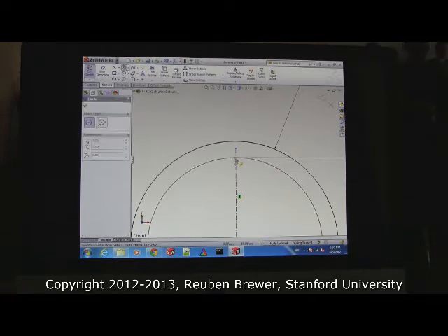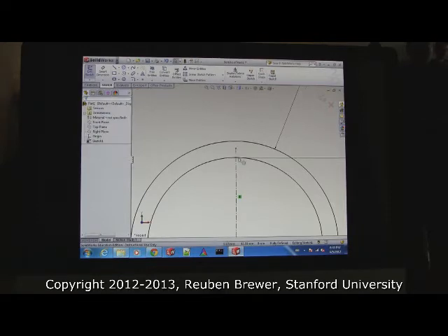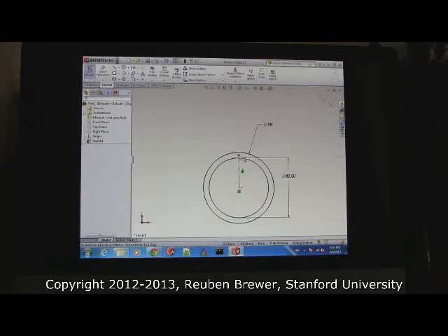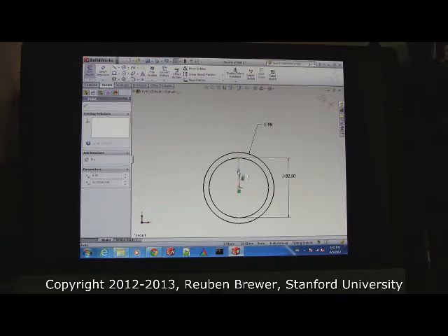Okay, so go ahead and put a circle. And by the way, there are no trivial details or questions too stupid for SolidWorks. If we don't get the beginnings now, it's going to be a really long quarter. So if you have any question at all, just ask it. It's totally fine. I can make my line smaller and bigger. If you want to make your line smaller and bigger, just click on the end and drag it.